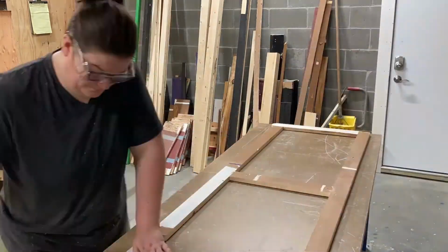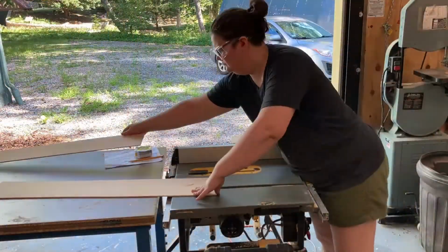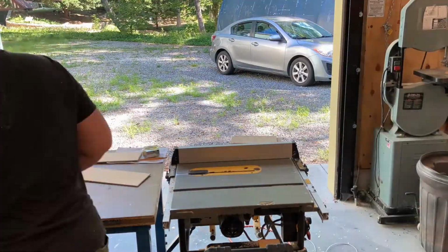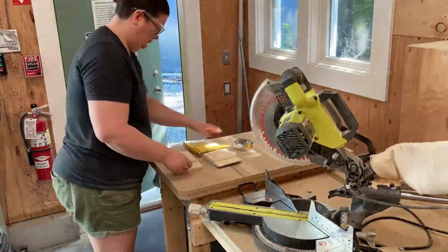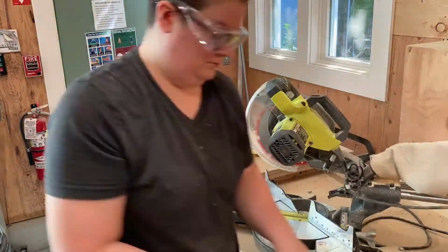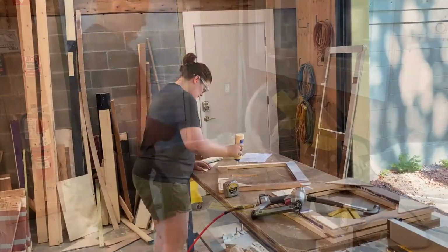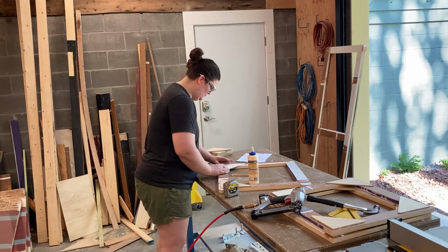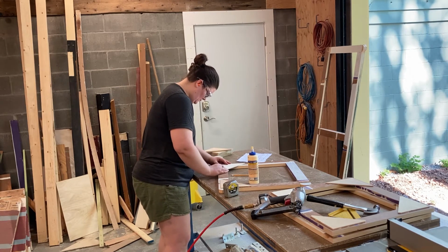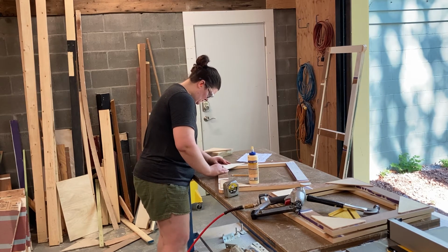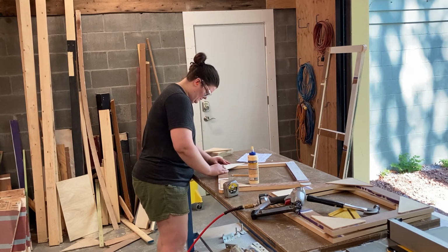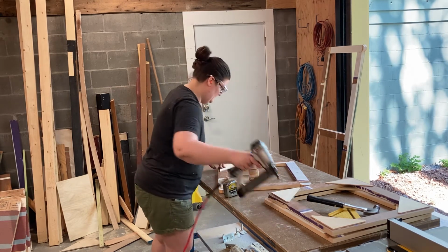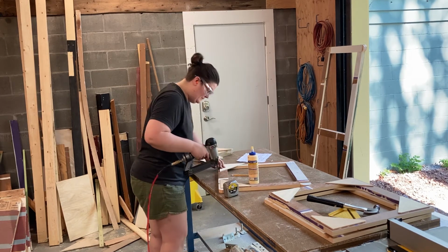Flat frames like this need some reinforcement in the corners, which serves as bracing to keep the frame rigid. Thin plywood is often used to create keystones and corner blocks. I did not have any quarter plywood on hand, but I did find some scrap Luan, which is acceptable for this demonstration. When creating corner blocks, you want the direction of the wood grain to run parallel to the long side of the triangle. I had to cheat these corner blocks a little smaller than usual in order to make best use of my scrap Luan.